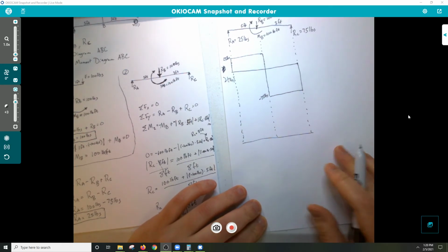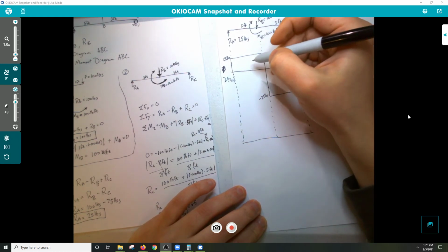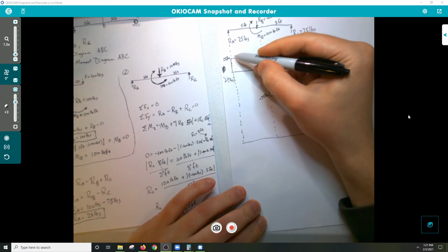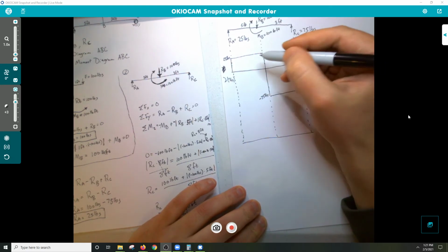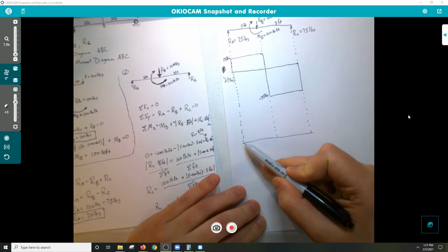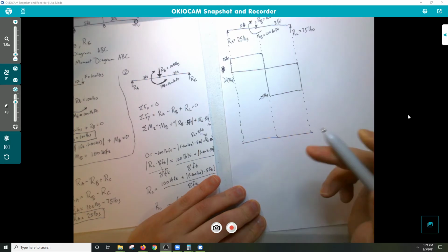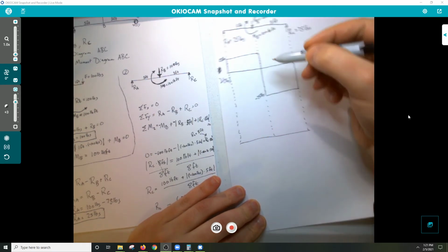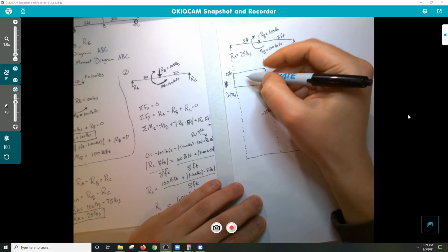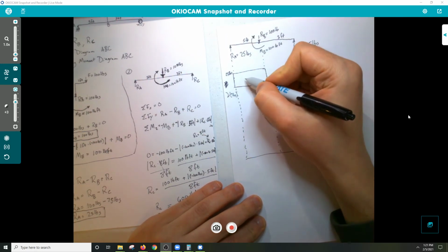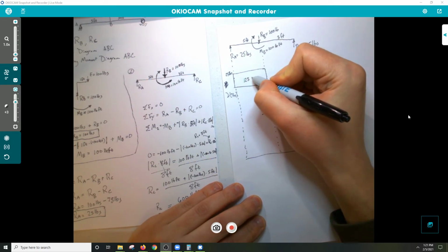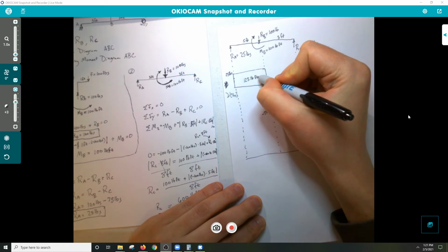Alright, so bending moment diagram. You guys are probably used to the areas here. Like you find the area, right? 25 pounds times your 5 feet gives you how much of a rectangular area, that slope you get, right? And where you're going to end up by the time you get to point B. So we find the area, which is 25 pounds times 5, which would give us 125 pound-feet.